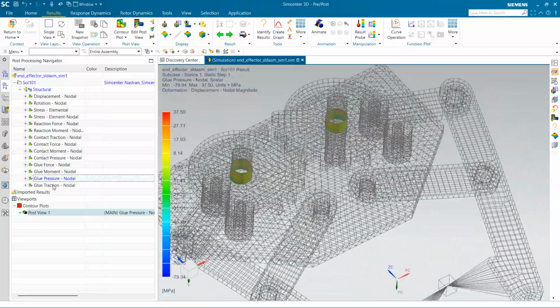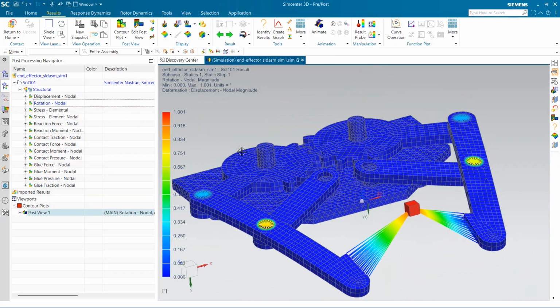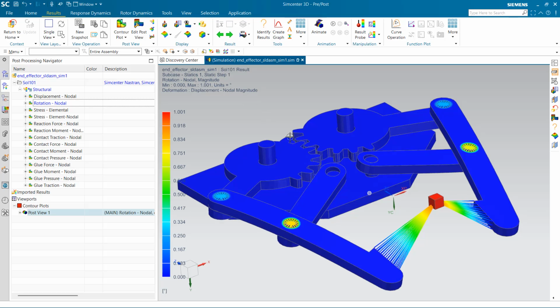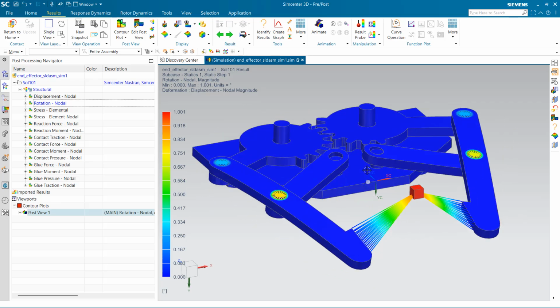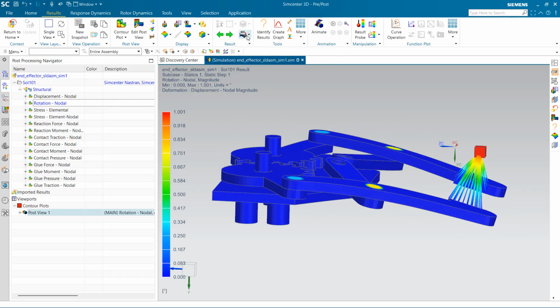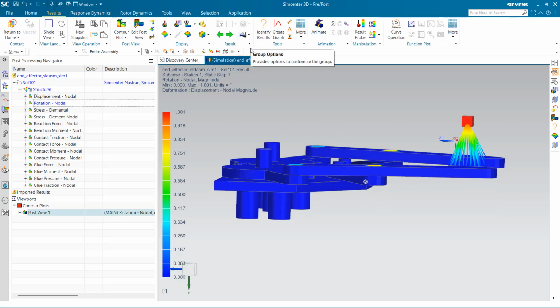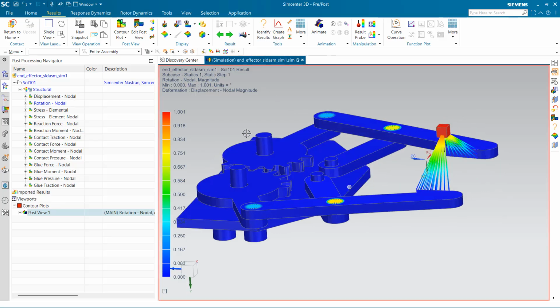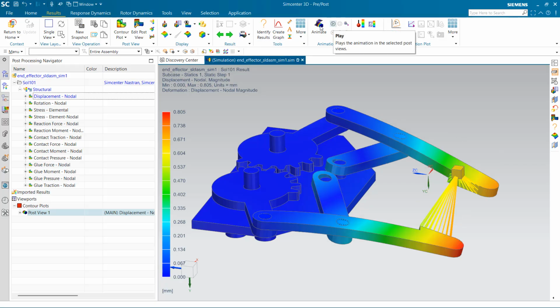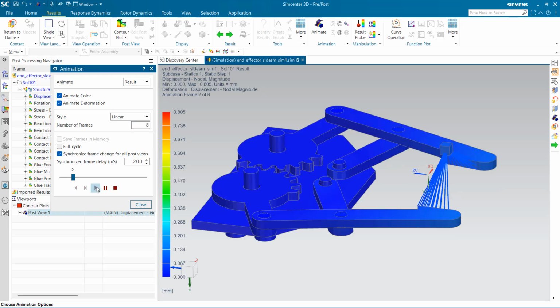Okay. So you can try to toggle the external and features to make it nicer. But this is also an exaggerated displacement. You can change to absolute percent. Okay, so this is the actual displacement. Then you can try to maybe toggle back to 10%, and do the animation. So this is the animation.